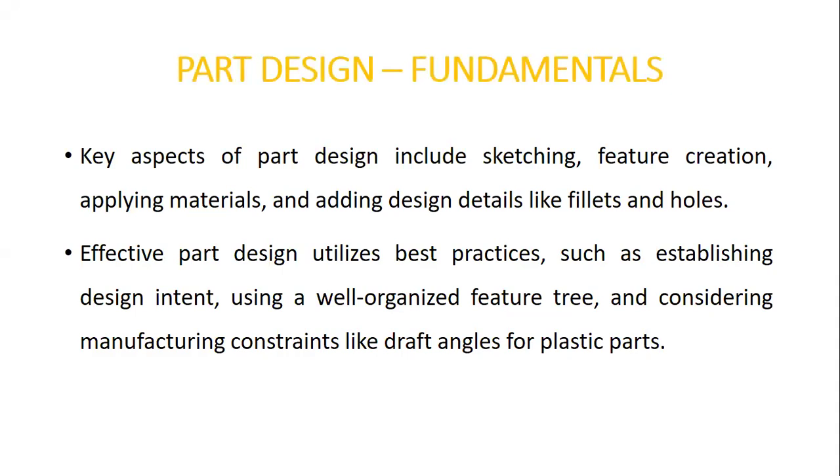What are the main key aspects of part design? It includes sketching, feature creation, applying materials, and adding design details like fillets, chamfers, and holes. Effective part design utilizes best practices such as establishing design intent, using a well-organized feature tree, and considering the manufacturing constraints like draft angle for plastic components.